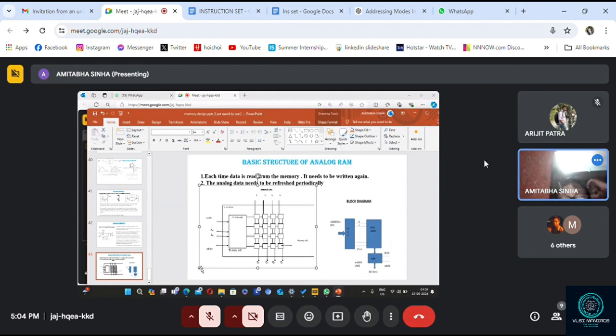Now this can be done in two ways. Whenever the data is accessed from analog memory, then through an A to D converter, temporarily you store it in the digital data memory. After that, you store from there to analog memory. Otherwise, in the circuit, you have to have some analog kind of register where you have to store, and again from there you have to store all this. So that is why here we have used an A to D converter and a D to A converter within the processor.